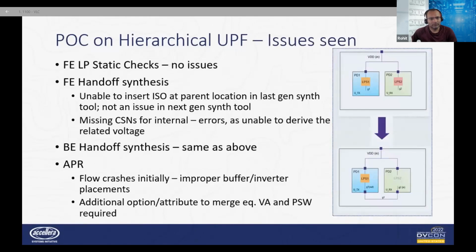So in front end, the low power static check tool, we saw no issue. During front end handoff synthesis, the previous gen synthesis tool was unable to insert isolation if the location was parent. We filed a ticket on the vendor, and also parallelly we tried out the next gen synthesis tool, and we didn't see the same issue there.